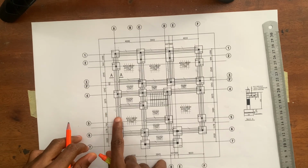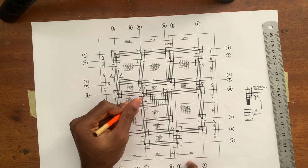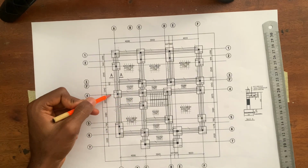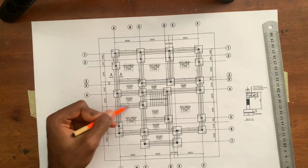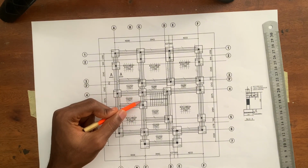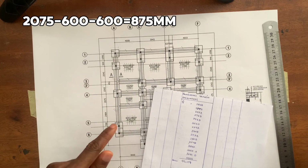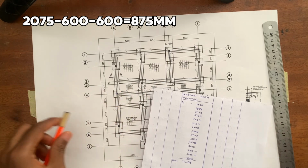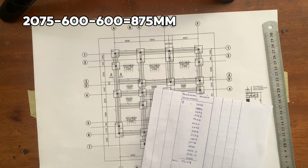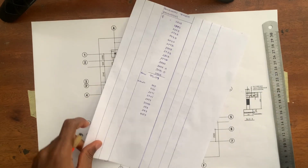The next one we're going to work on now would be this small one here, this part here. We know that the call out from 4 down to this midpoint is 2075. We're now going to be minusing half of base type 1 from both sides. Half of the length of base type 1 is 600, so by 2 will be 1200. We'll minus 1200 from this 2075. That's 875. So the distance from here to here is 875. We'll record.